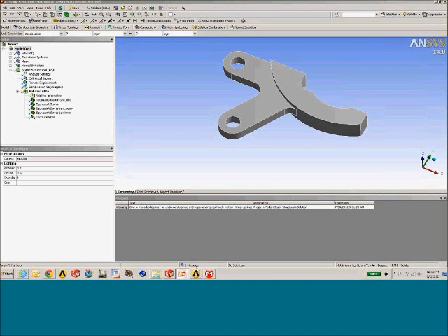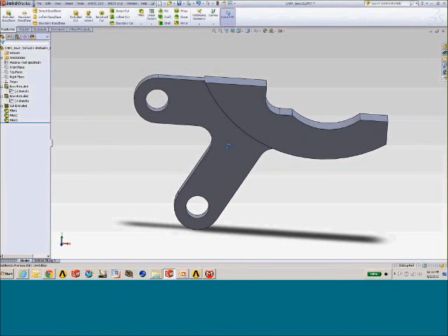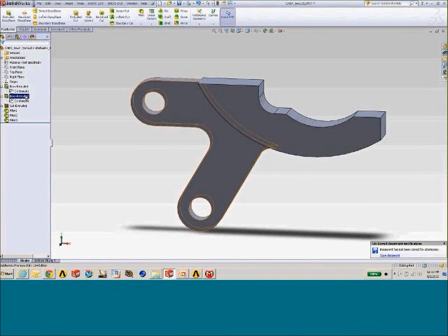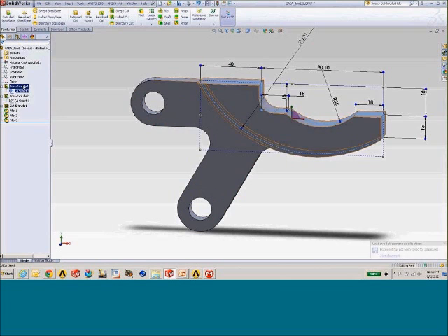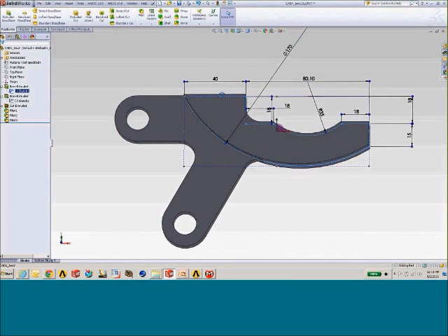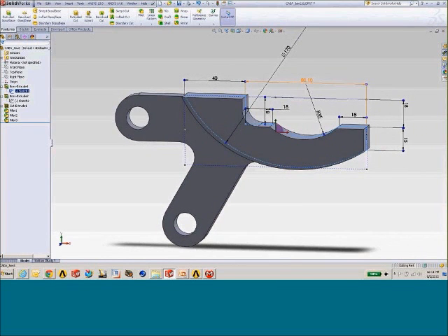I'm going to locate these on the CAD side. So let's pop up our SolidWorks model here. And our CAD parameters are found in the details of our sketches as well as in the details of the modeling operations that we perform. So just right off the bat here, if I click on my first sketch, I have a series of dimensions that all could potentially be brought over to the analysis environment as a parameter.